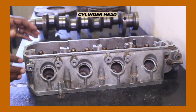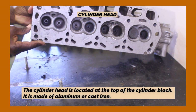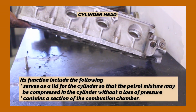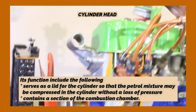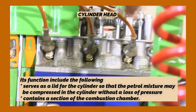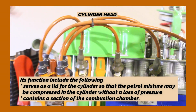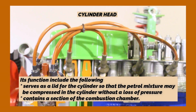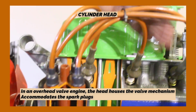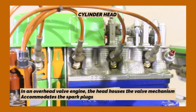Cylinder head. The cylinder head is located at the top of the cylinder block. It is made of aluminum or cast iron. Its functions include the following. Serves as a lid for the cylinder so that the petrol mixture may be compressed in the cylinder without a loss of pressure. Contains a section of the combustion chamber. In an overhead valve engine, the head houses the valve mechanism and accommodates the spark plugs.